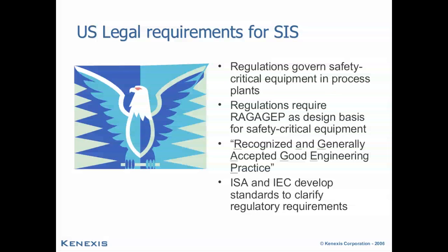And the role of the ISA and more broadly the IEC, the International Electrotechnical Commission, has been to clarify the regulatory requirements for safety instrumented systems by offering the ISA's S84 standard, which has now been harmonized with the IEC's 61511 standard, and to offer that as the means to describe what is a good engineering practice, one that's recognized throughout the industry, and furthermore, one that has been generally accepted by many operating companies within the industry.